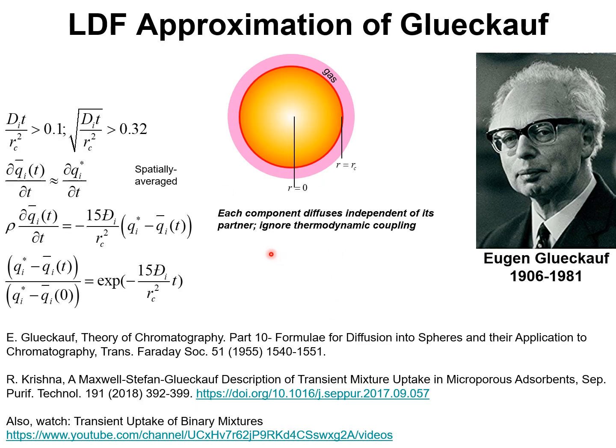Rather than solve the partial differential equation describing transient uptake within the crystallites using the Maxwell-Stefan diffusion equations, most commercial software, such as those marketed by ASPEN, ProSim, and others, adopt the so-called LDF approximation, where LDF stands for linear driving force.